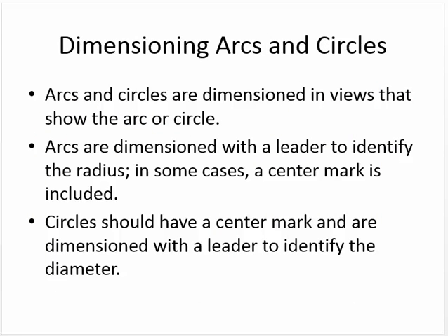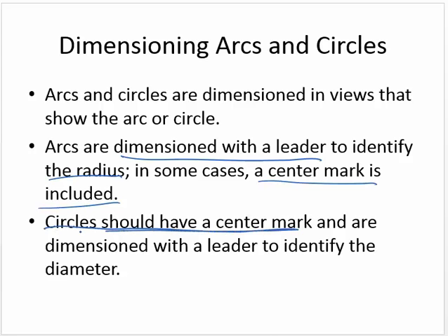Okay, things I want to point out to you here. Arcs and circles are dimensioned in views that show the arc or the circle. Arcs are dimensioned with a leader to identify the radius. A center mark is sometimes included. Circles should always have center marks, and are dimensioned with a leader to identify the diameter. So we need to have this leader.